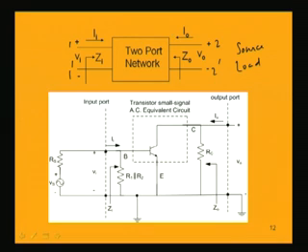And from this knowledge of Vi, Ii, V0, I0, we can find out the input impedance. Input impedance means Vi by Ii, that is equal to Zi, and it can be found from this ratio. Similarly, at the output we can find Z0, V0 by I0 is Z0, the output impedance. We can find out voltage gain V0 by Vi, and we can find current gain, all these quantities which are very important for an amplifier, and these can be found by considering the whole transistor amplifier as a two-port system, which we will be using.